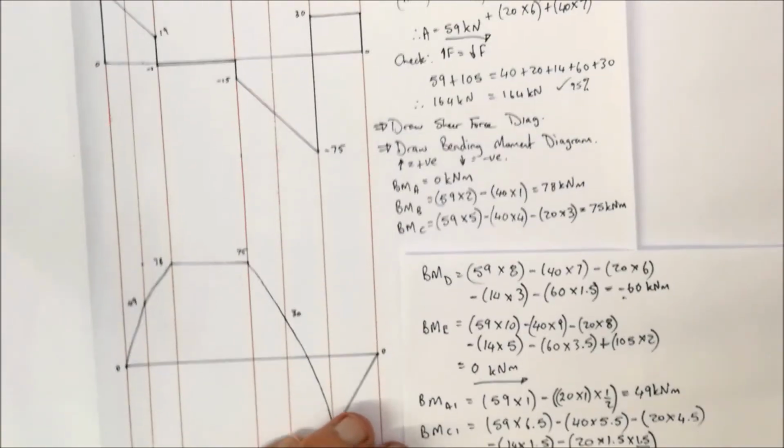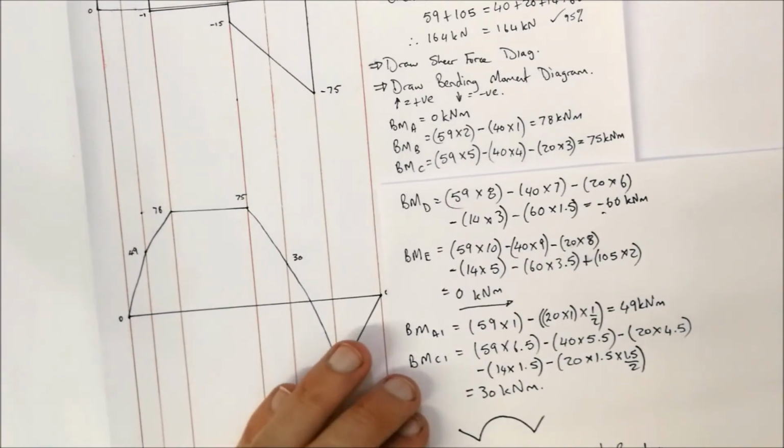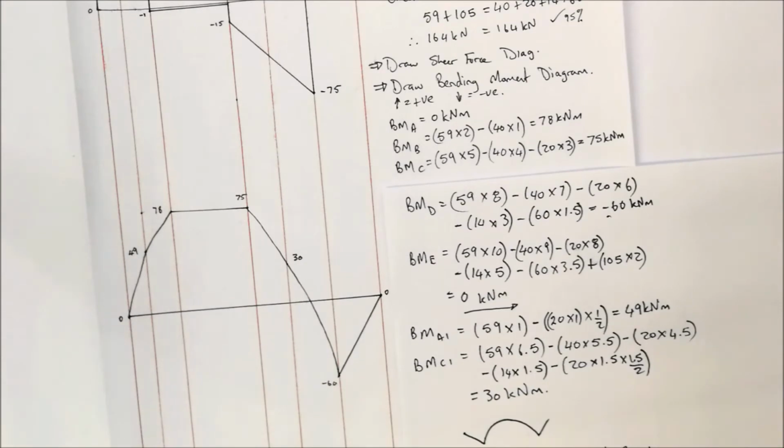Right. Having a look at this, essentially it's the same principles that you're going to follow. You can get so many different scenarios with your beams. You can have the distributed load going across a whole beam, and the same principles will occur. You'll look at the middle of each distributed load, act a force on it, and calculate what it would be. So if it's 20 kilonewtons per meter, look at the distance and multiply it by 20.